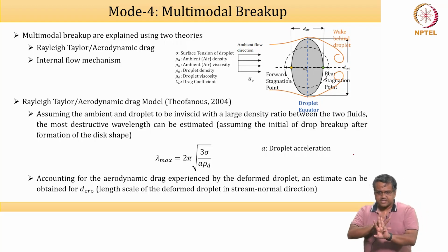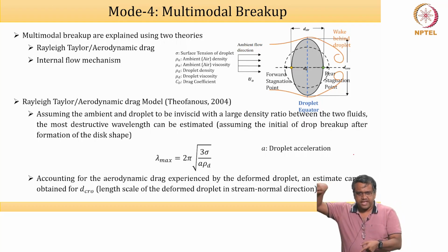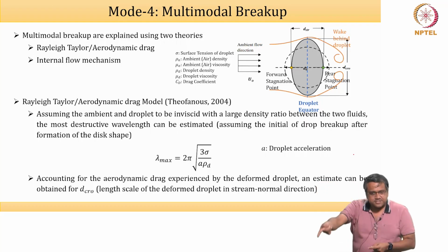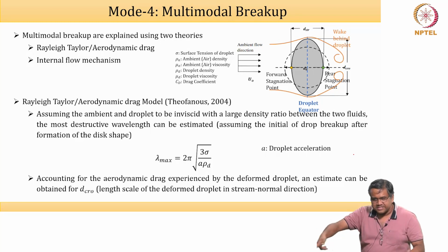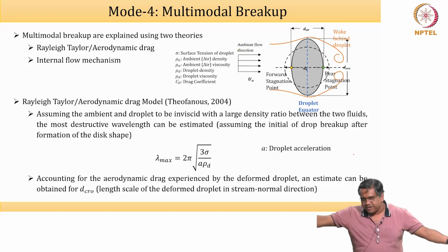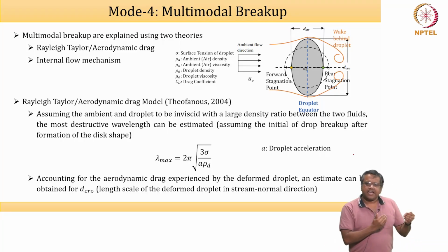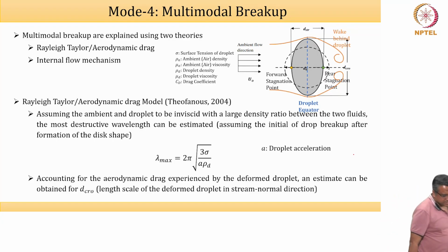So the droplet, as it accelerates, it's a high density fluid accelerating in a low density fluid, you create perturbations, and then the Kelvin-Helmholtz dances on the top of those perturbations. So it's like it dances on a stage that is prepared by this, okay, with a little bit of a phase lag between the two. Dances on the dance. So it's like the gravity kind of a phenomenon. You dance on a curvilinear kind of a space.